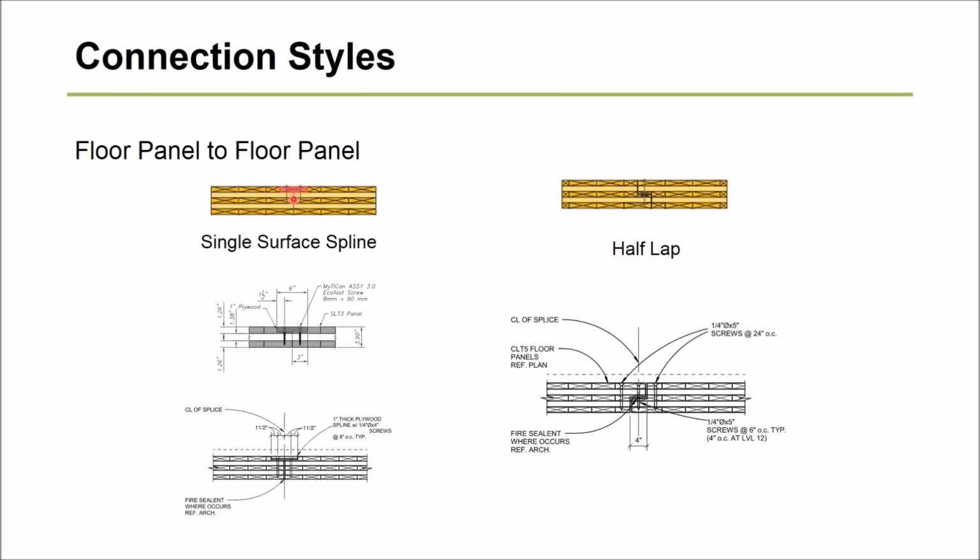The surface spline really is the primary mechanism to share shear loads or diaphragm loads. But in the surface spline, you can also come through with long screws running horizontally to create more of a vertical load connection between those panels as well. These things come together quite simply. The surface spline can also use nails as well as screws.